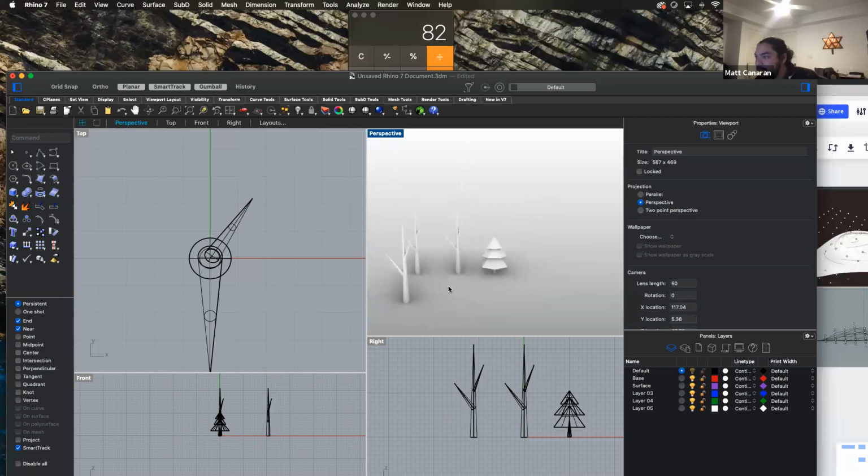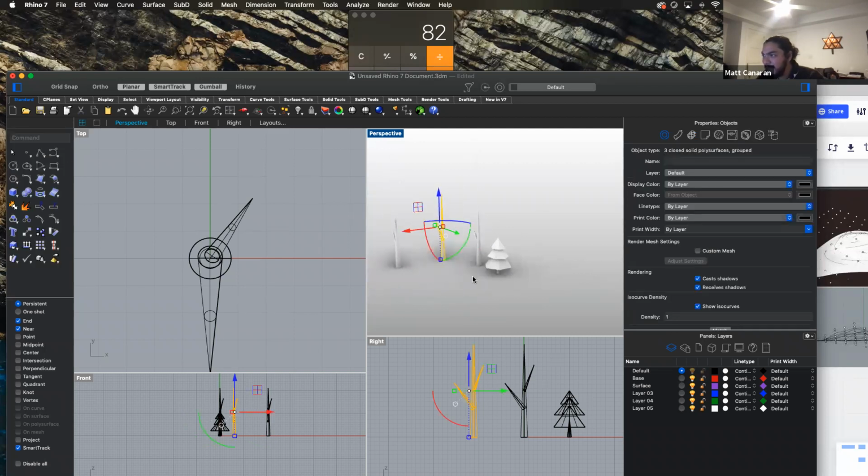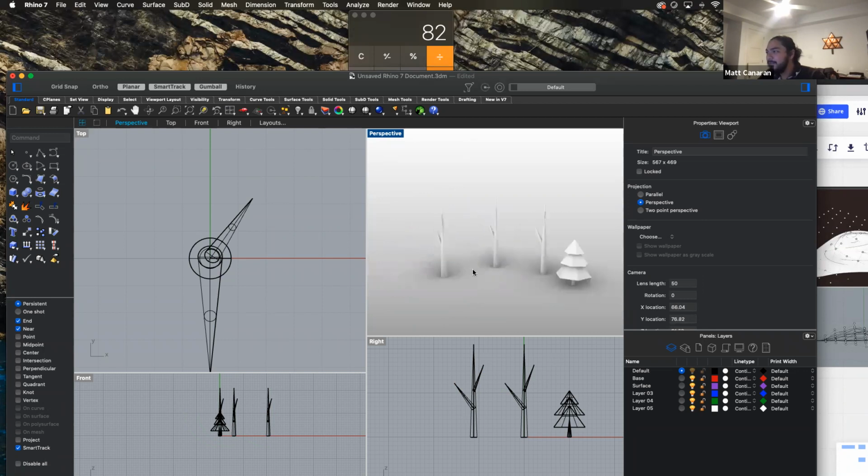Okay, so that's that. While we're here, I just did one thing. I don't know if you guys caught this, but I selected using the top down. So if this is just like AutoCAD, I just want to talk about selection for a sec. If I go from top left to bottom right, I only select objects that are entirely contained in my selection.